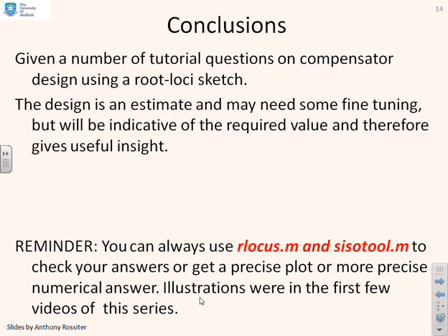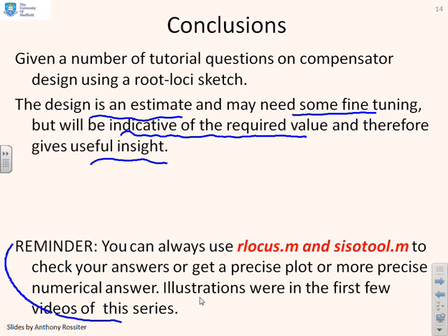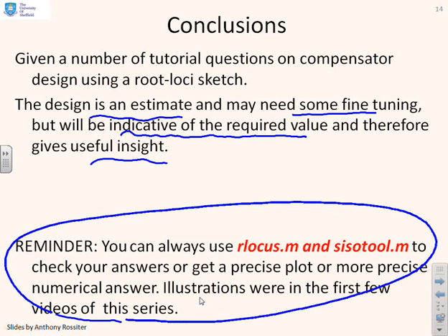So in conclusion, we've given a number of tutorial questions on compensator design using a root-loci sketch. And we should emphasize this design is an estimate, and you may need some fine-tuning, okay? But the point is, it's indicative of the required value and has given you useful insight. If the K that you've tried to apply is a long way away from this, you're probably way away from where you need to be. If you really do want precise answers, remember you're recommended to go and use appropriate software tools.